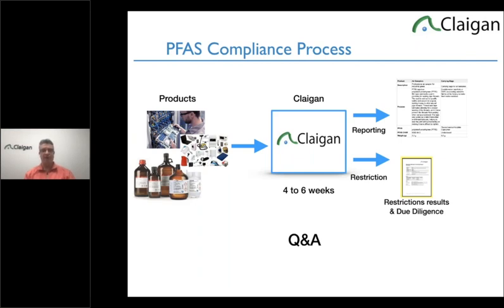Tons of things that transfer fluids have Viton, FKM, very commonly as a gasket material, super common. Anything that needs chemical resistance is full of fluoros because that's the main chemical resistant material. It can handle oils and waters, which is not common. Silicone can't do that. Polyurethane can't do that.